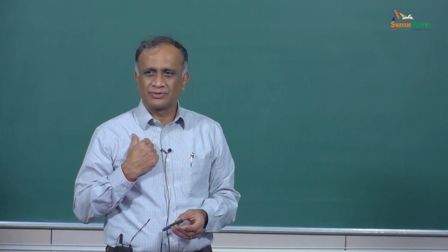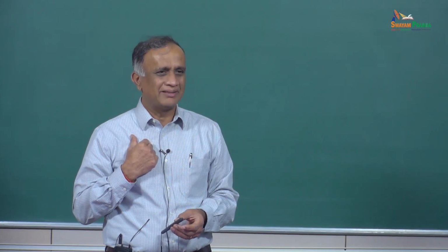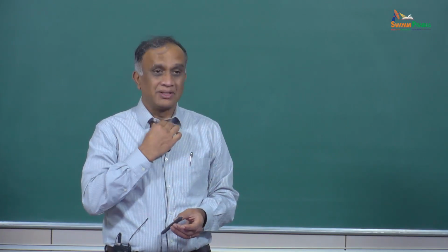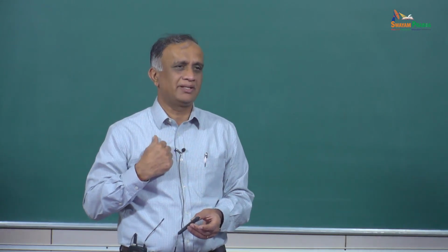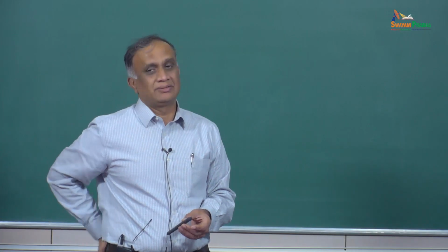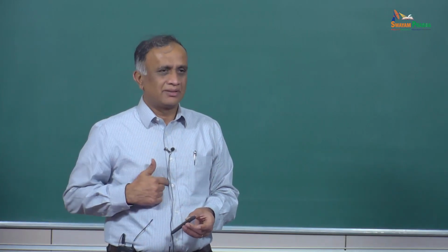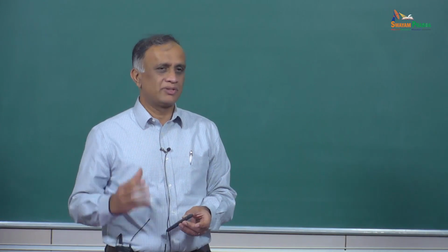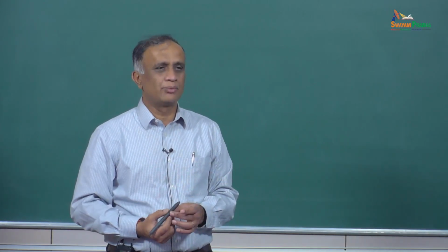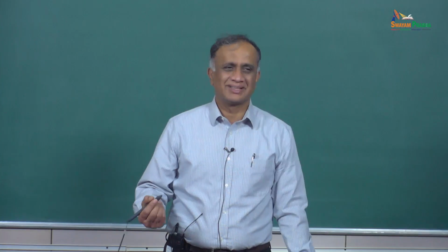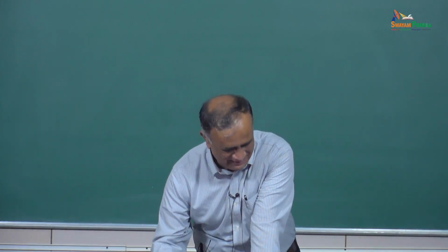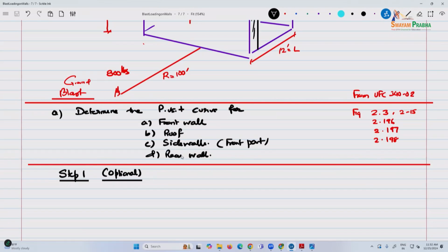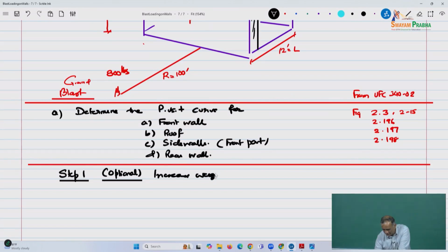So they enforce ductility in various ways. I think maybe IS 456 also does that in some way, but especially since 2014, ACI 318, for the last 10 years, the code that's applicable, the ductility is enforced with strain limits, and there are several ways they enforce that. So I thought there's perhaps truth to that story all over the world. So it's optional, we increase the weight, whatever you feel good.